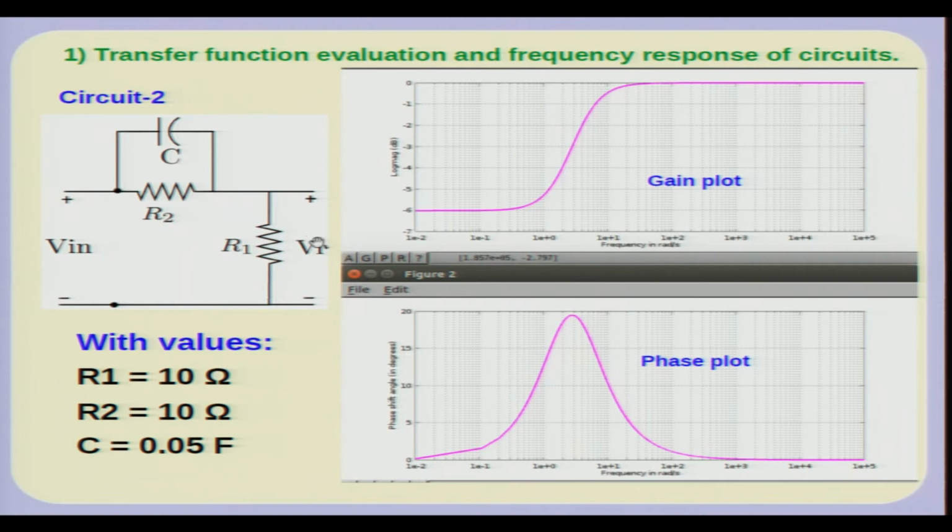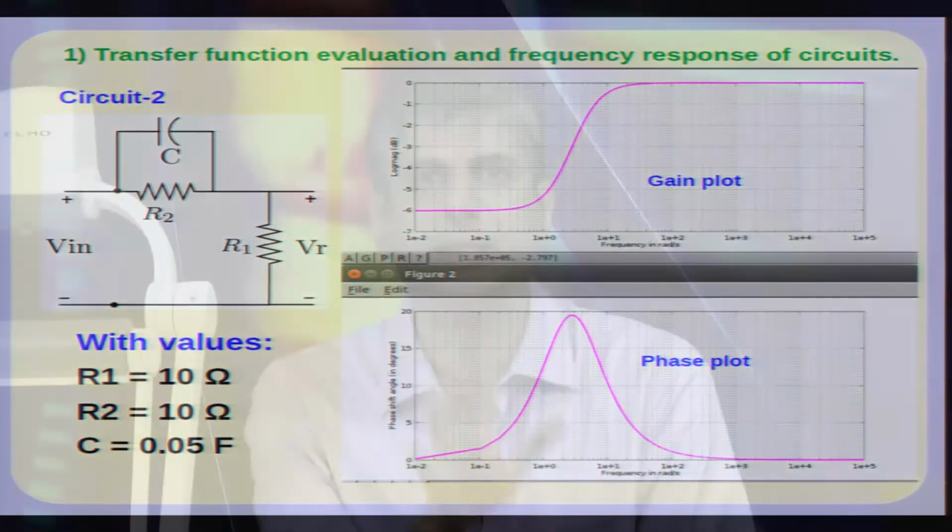In our circuits we have so far been biased towards getting the transfer function between current and the input voltage. This is also called the impedance transfer function, but you can have other combinations depending on the nature of the circuit. You could have an input as a current source, but remember a current source cannot be in series with the inductance. You could have a circuit in which the input is a current source and you obtain the voltage across some point. That is called the admittance.